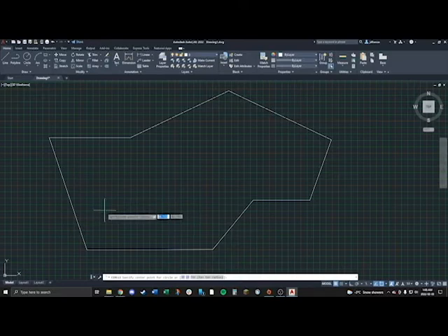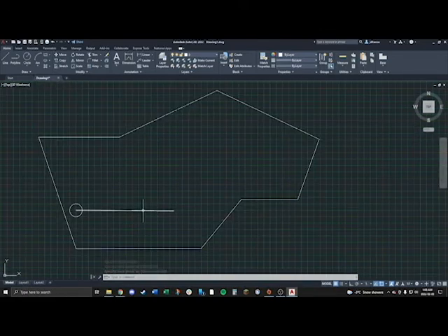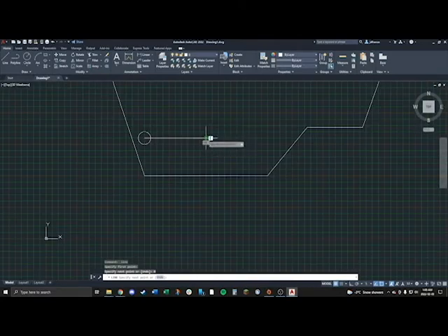So our first circle, let's put it at 80, tab 80. It is important that you do this, especially for angles. I'm just going to put this at 5 as a radius. It is important, especially with lines, that you specify 0, because if you notice here, if I put 48 and enter, that shows up as 0 to me. However, if we look on the line, it is off by a little bit. So if we do the same thing, except we tab and input 0, it will always lock exactly on, no matter how close we zoom.